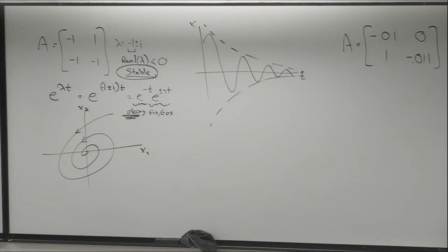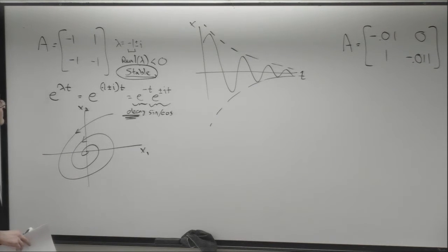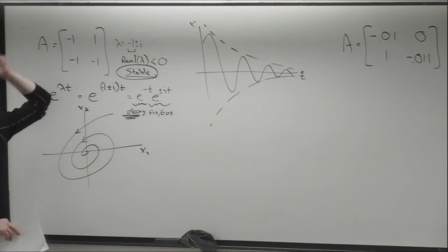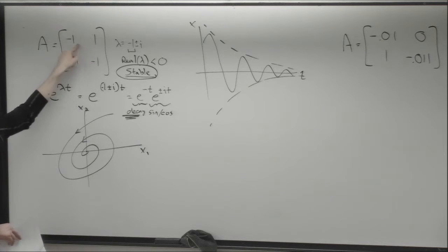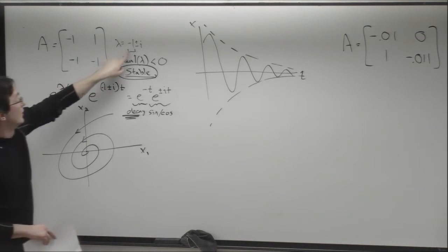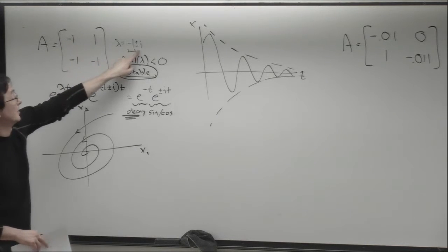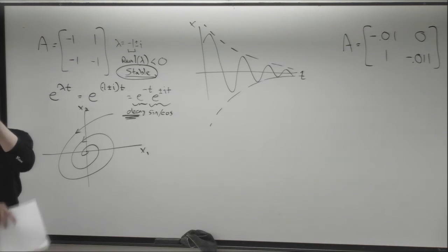Yeah. So maybe I can't recall, but the other terms that are not on the diagonal, -1 and the 1. Are those physically damping terms? No, so the diagonal -1 terms are the damping terms. So if you compute the eigenvalues of this, you'll find that the negative part comes from these diagonal -1s, and the oscillatory part comes from the off-diagonal, equal and opposite plus and -1 terms.